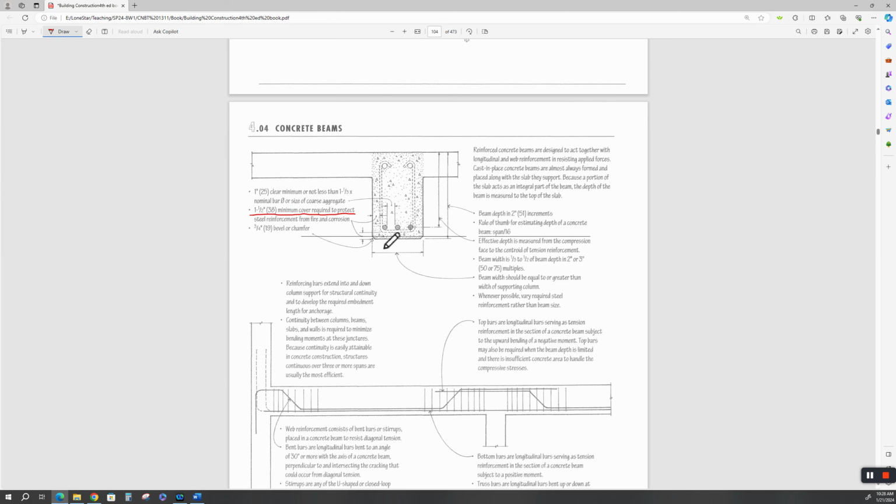And you designers, don't forget that 3/4 inch bevel. If not, that's going to look like nasty stuff. You want that bevel. And what they do, they'll come in here with the form, and they'll have a bevel strip, a wooden bevel strip, and all this gets sprayed with form release agent. Then they'll lay that steel cage in there for the beam, and they'll have to have rebar chairs in here. Most of them are plastic now.